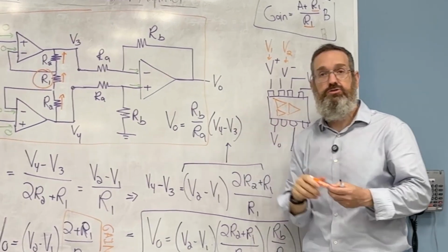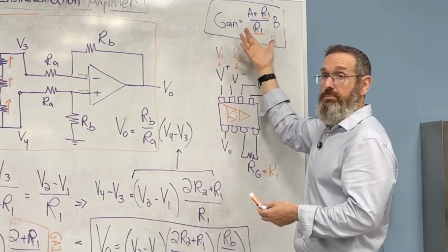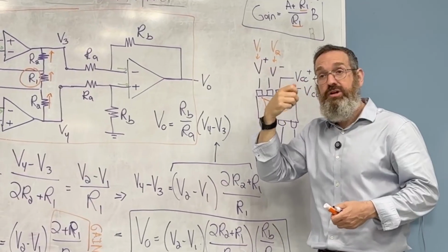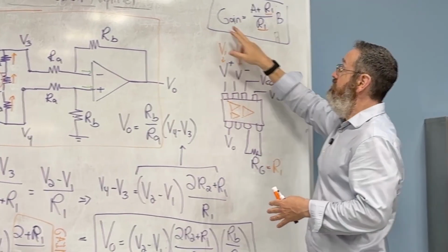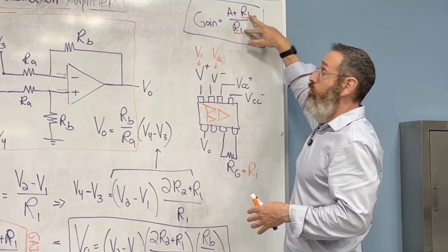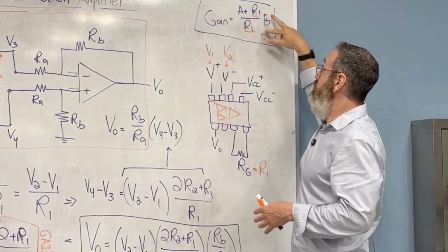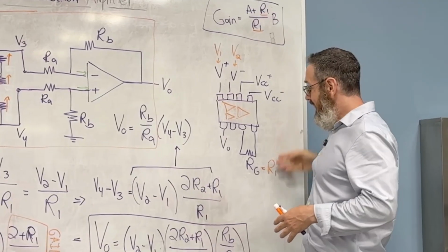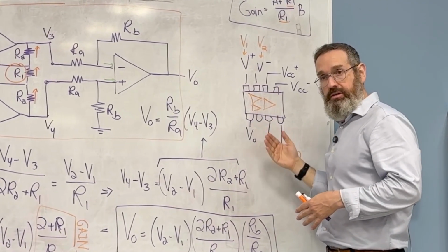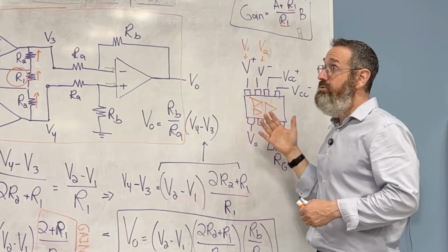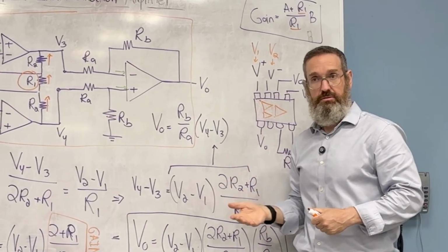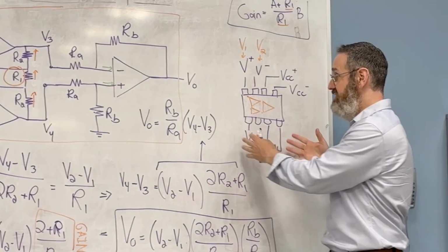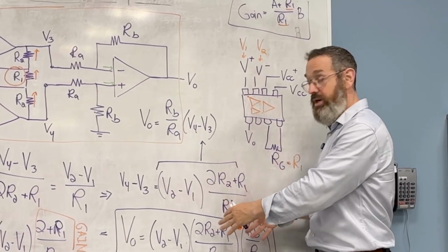Just grab 1 resistor and put it in. And this is not such complicated math. Just do the math and you get any gain you want. 1, 10, 13.5. Just select the gain you want, and with one equation, 1 unknown, solve for R1 and insert the R1 into your circuit. So the instrumentation amplifier is, I believe, the simplest circuit, right? It asks very little of you for what it gives you.